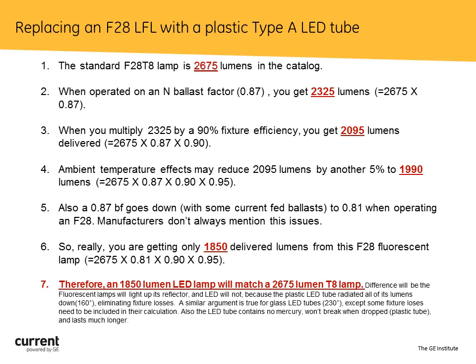If you go with a glass tube, you are going to have some fixture efficiency impact. So instead of 90% efficient, you might take off 3 or 4 or 5% reduction in those lumens because of the LED actually using the reflector and bouncing light off of it and therefore losing some of its light.